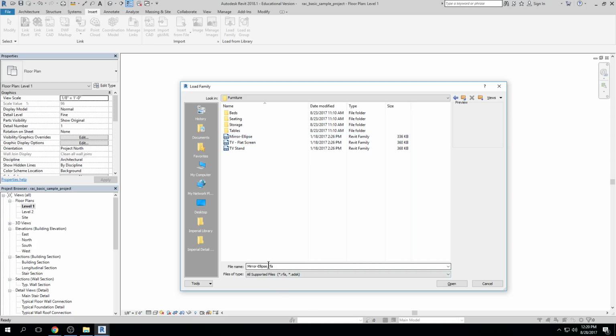So right here, Revit families are going to be RFA. All right. So if you have a Revit file and you've started working in it and it's .rfa extension, you're working in the wrong file. Okay. A lot of times you can still do a lot of things you can do in Revit regular working files, but things are going to go wrong, obviously, right? So these are Revit families. They're like blocks, essentially, in AutoCAD, okay?